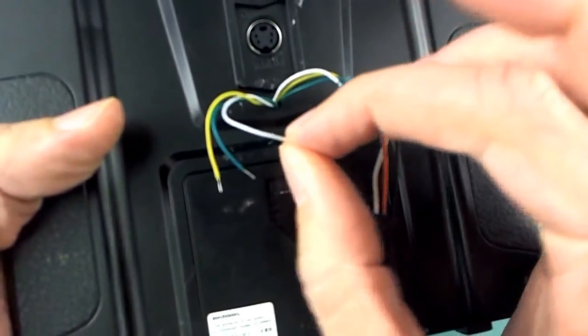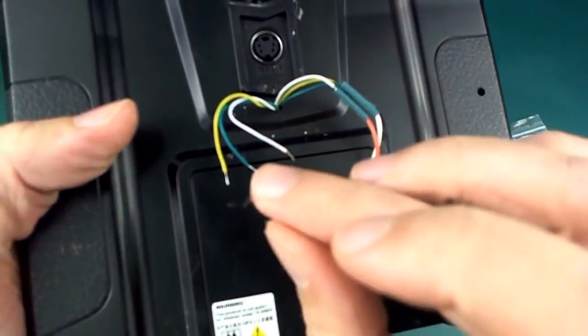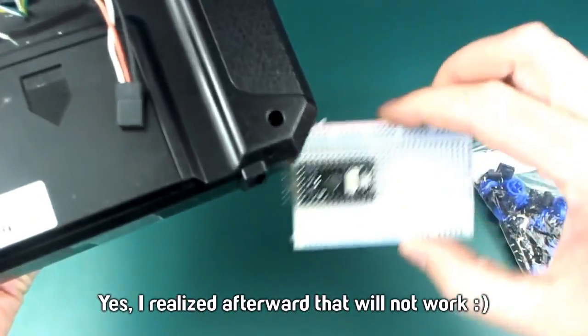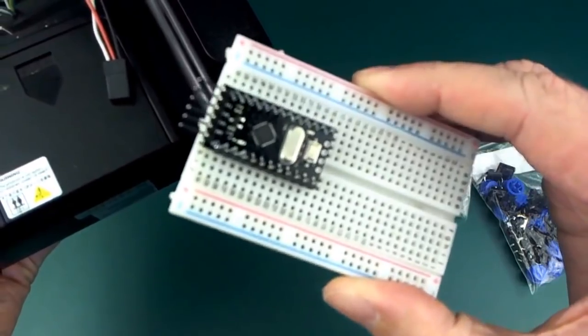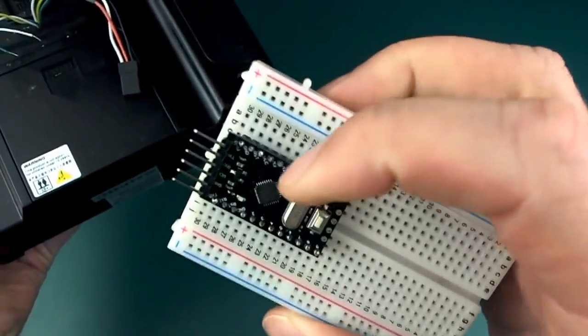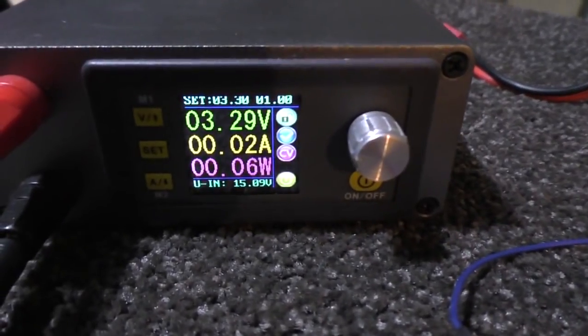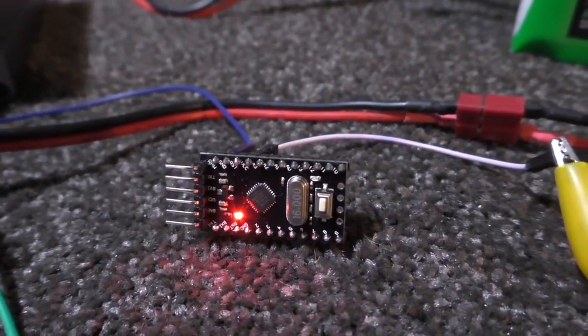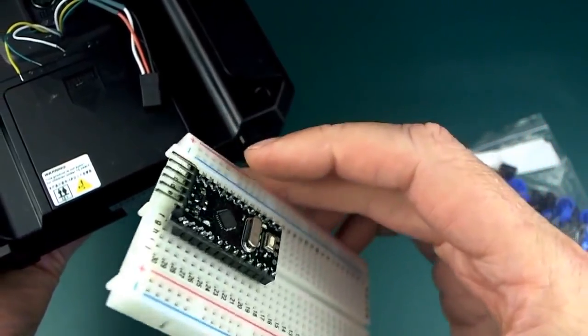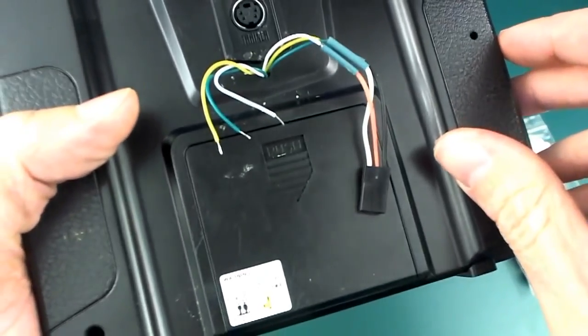Now this being 3.3 volts here, what I'm going to try and do is run my Arduino off that. Even though I'm using what we typically call a 5 volt Arduino, if you power it from the VCC pin there, you can use 3.3 volts. I did a quick little test before, and it powers up, at least it runs the blink sketch, so it looks good at this point, but I'm not really sure if it's actually going to work fully for this project, but we shall find out.